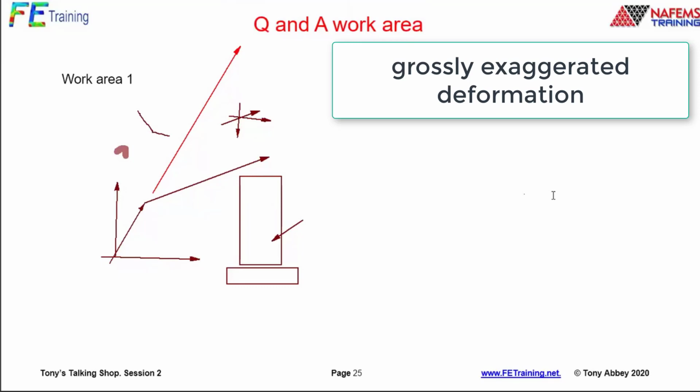So a typical approach taken in post-processors is to say this is the screen dimension, and then take the leading dimension of whatever the object is. My deflection is going to be typically 10% either of that leading dimension or 10% of the screen diagonal. So sometimes they use the screen diagonal and say 10% of that, and that's the actual deflection that we see there.